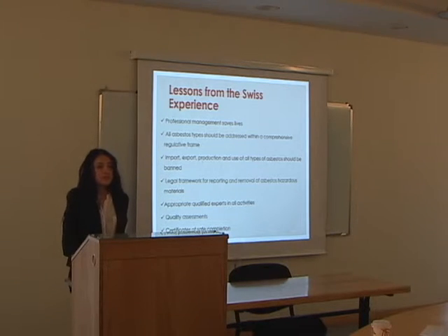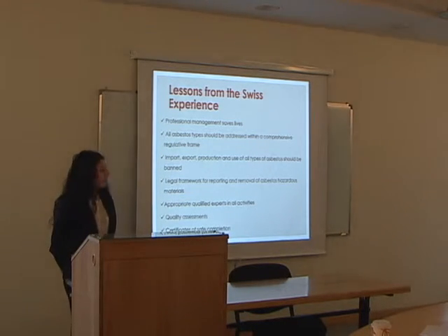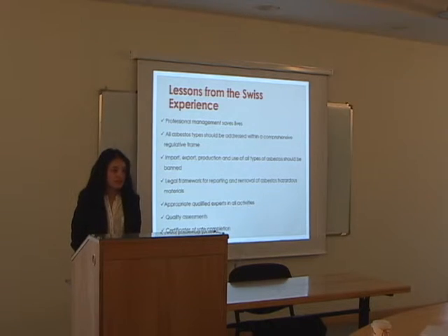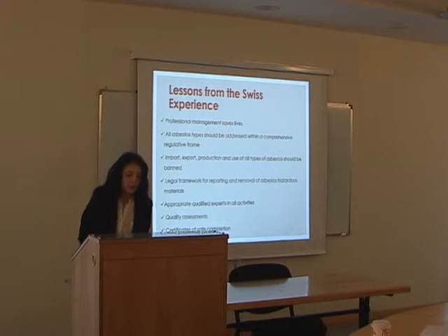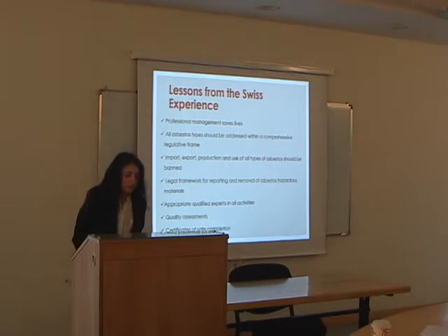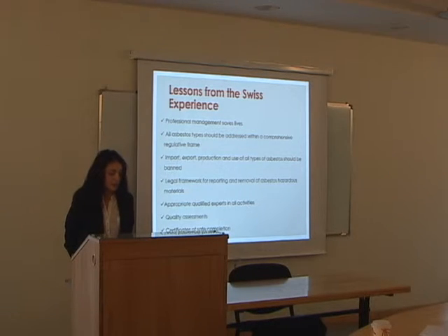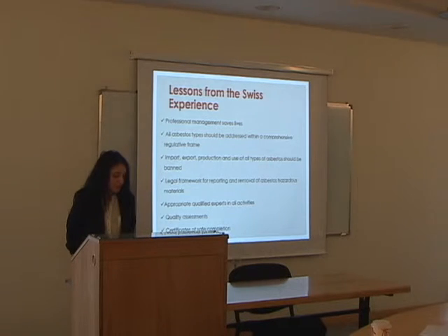And some lessons and recommendations from the Swiss experience. Professional management of remediation actions is very important for them. All asbestos types, according to them, should be regulated in a comprehensive regulatory framework, and import, export, production, and use of all types of asbestos should be banned all over the world. And legal frameworks should exist for reporting and removal of asbestos hazardous materials. Appropriately qualified experts should be included in all activities, quality assessments should be done very often, and certificates of safe completion should be given.